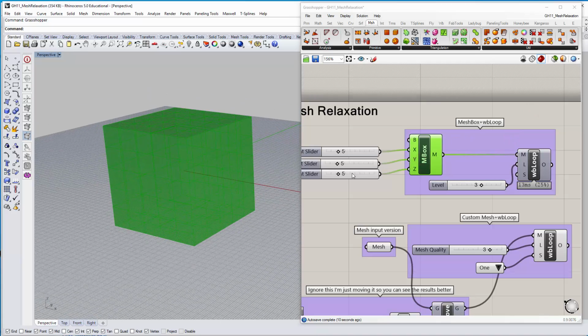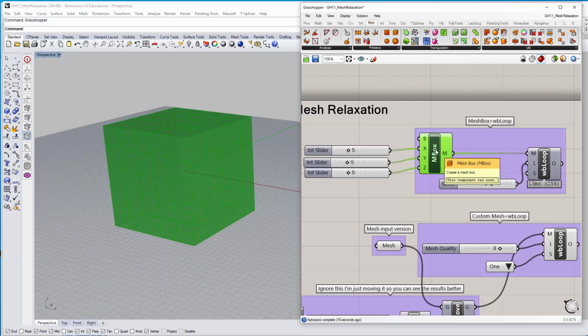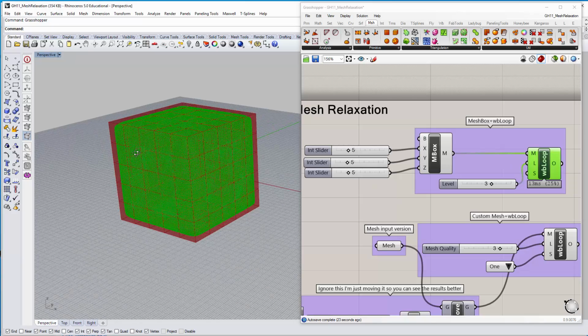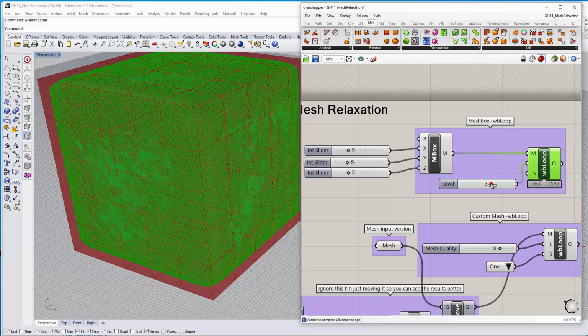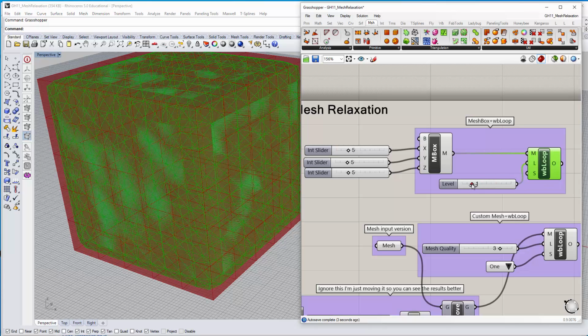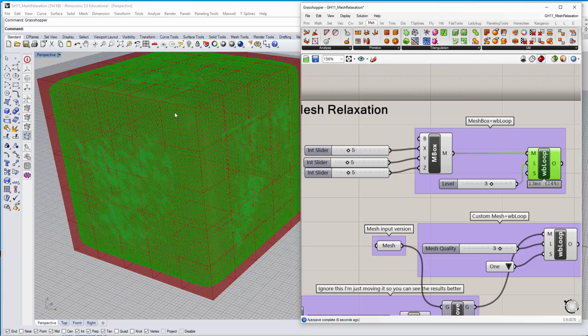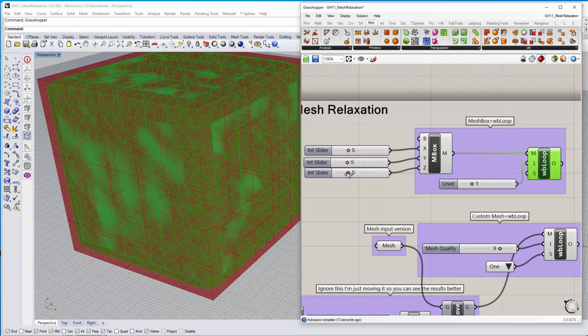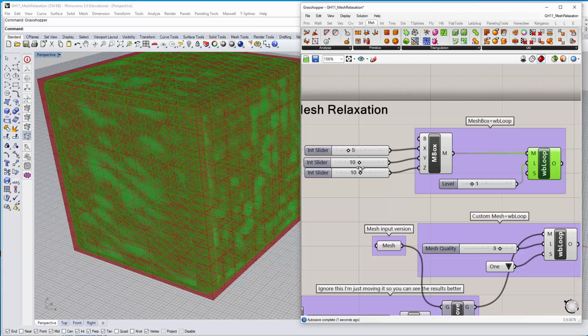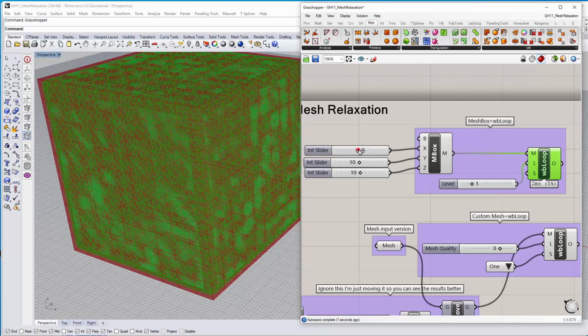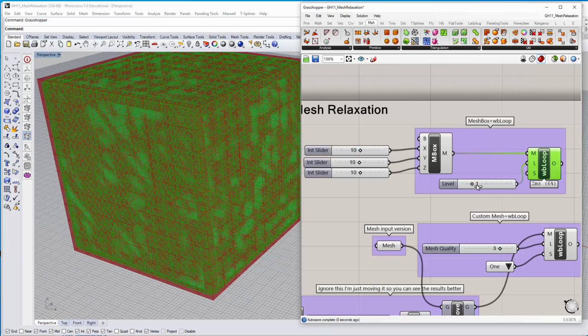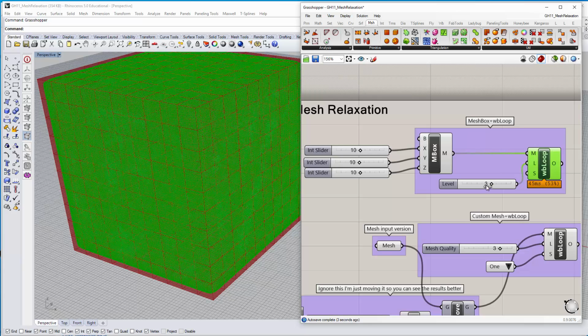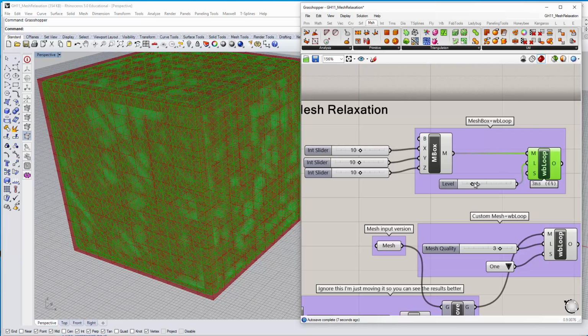Okay. So what bearing does that have on this? Well, there are two variables to this. One is, you'll see that the Weaverbird loop subdivision, which is the green thing in the center that we saw before. Let me simplify it a little bit. So you see, as I do more subdivisions, it kind of rounds a corner, it loosens or relaxes things a little bit. It also has a lot to do with how many divisions are in the original mesh as well. So when this is much higher, so it's a 10 by 10, then this actually doesn't loosen as much or doesn't relax as much.